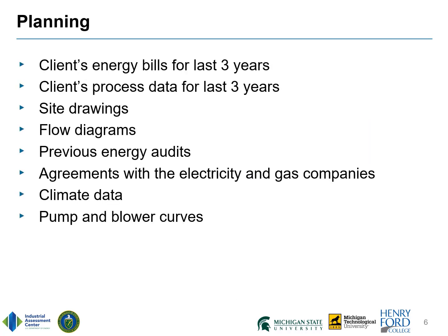Before beginning a process energy audit for a wastewater treatment plant, it's important to request from the client energy bills and process data for the last 3 years. Process data should be available if the system is using a SCADA. Additionally, it's important to obtain site drawings, flow diagrams, results from any previous energy audits, agreements with the electricity and gas companies, climate data, and pump and blower curves.